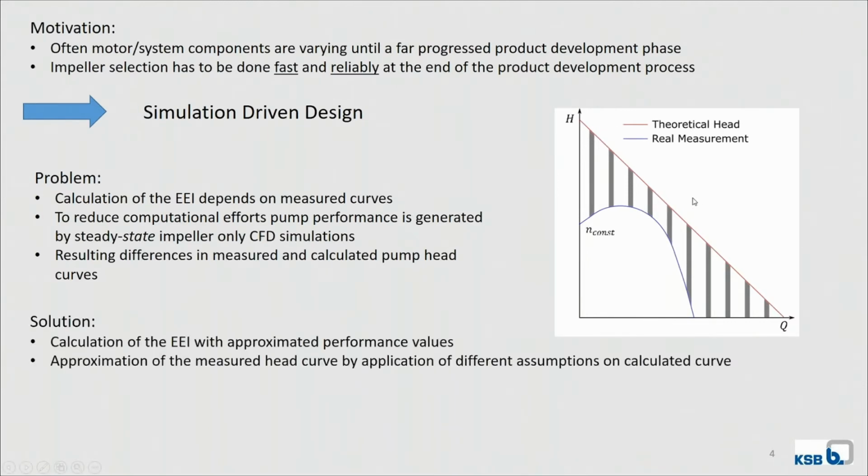CFD calculation gives us only the theoretical head of the pump. Yeah, and the solution for this is we need to calculate the EEI with approximated performance values. The approximation of the measured head curve will be done by application of different assumptions on the calculated curve. Yeah, and what does it mean?